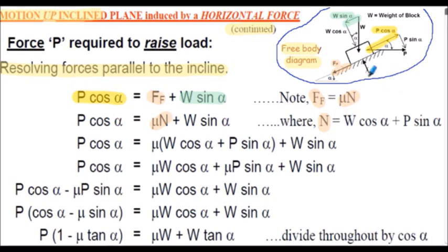Now resolving forces perpendicular to the incline, we can see that the normal force, labelled N here, in this direction, must be equal to W cos of alpha, this component here, in this direction, plus P sine of alpha, this component here, in this direction.